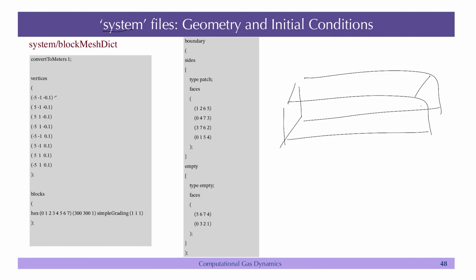Okay. And then you can say, okay, I only care about, let us say you can have this empty boundary condition on left and right and top and bottom. Okay. What it means is that it will not solve on top and bottom and left and right. So, let us say if you do not solve left and right, basically in the y direction, then you are solving a 2D problem at the center, right. If you, for example, put top and bottom also as empty, then it means you are solving just one line. So, we will show you that example.